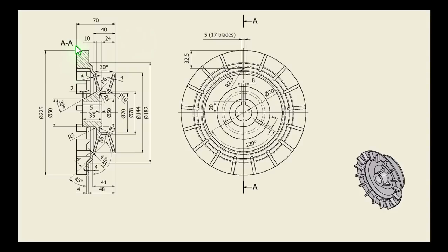We have to place a datum plane here at a distance of 70 minus 48 minus 4 if we start from this face. Let's do this.